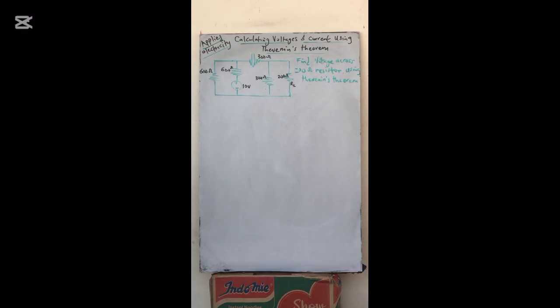That means the Thevenin resistance. So what am I saying? When we remove this voltage source, we are going to be having something like this. Now I'm going to calculate the Thevenin resistance. This Thevenin resistance is just the calculation of all the resistance either in series or in parallel. Let us study them one after the other.